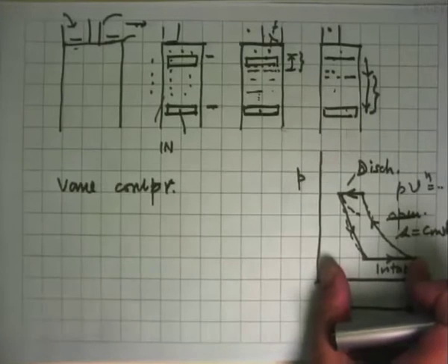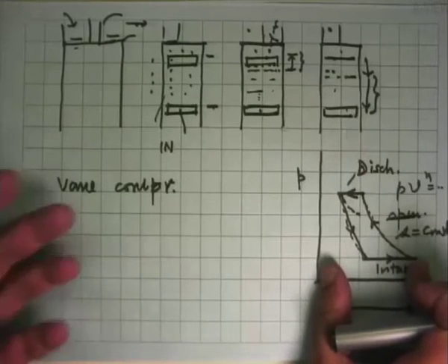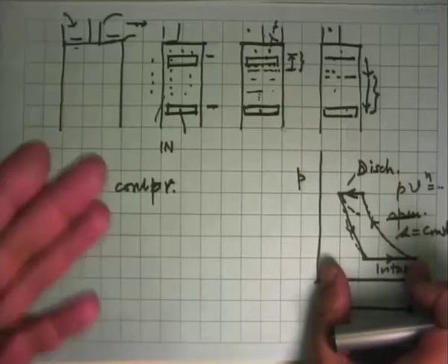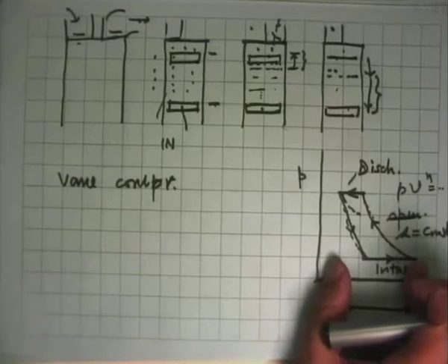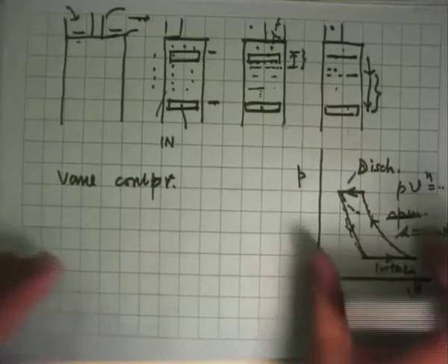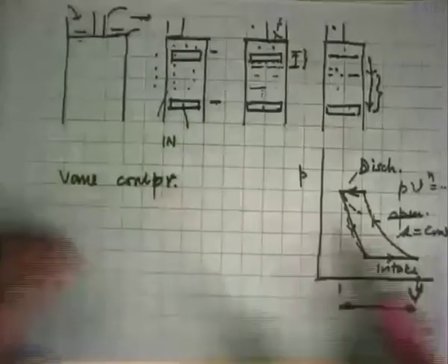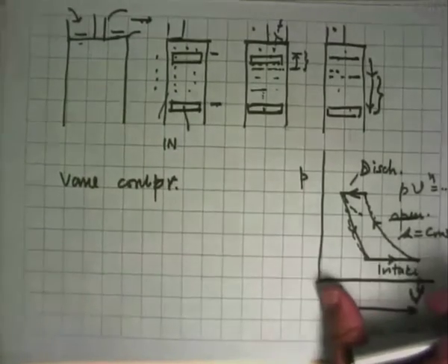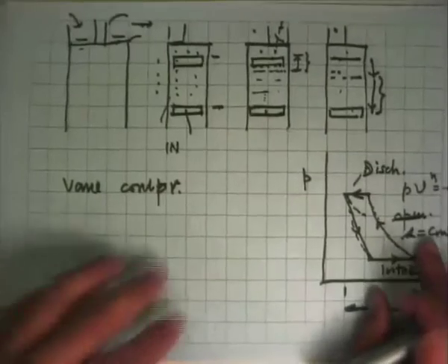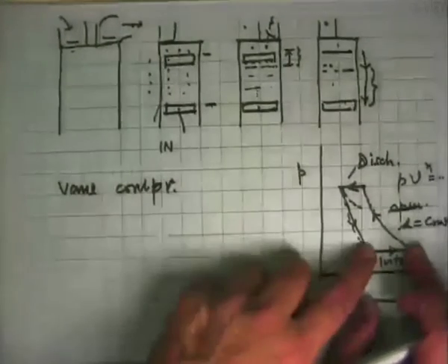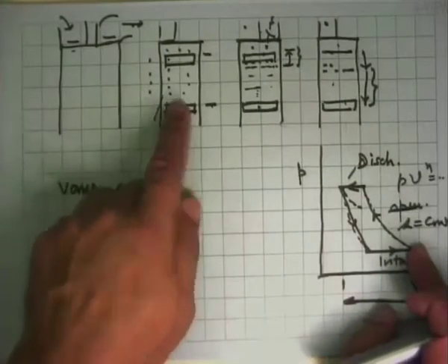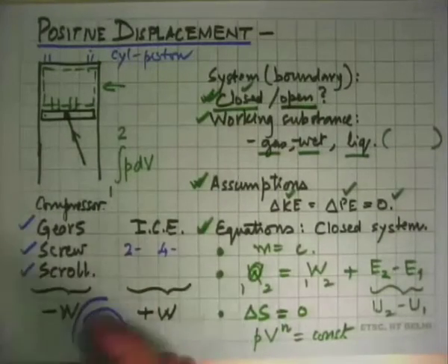The volumetric efficiency of these devices is very low. They are bulky, and screw compressors, pumps, or scroll compressors do this at much higher efficiency. So that is the reason why they are used, and they have already become much more popular than reciprocating compressors. So that's the reason for bringing it up in this discussion.